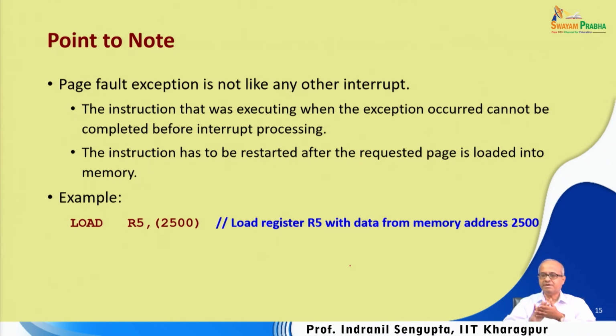Normally, suppose an instruction was executing, in the middle. If an interrupt comes, the instruction finishes execution, and only after that the interrupt is acknowledged. So, the hardware allows the instruction execution to complete, and only then interrupt processing will start.